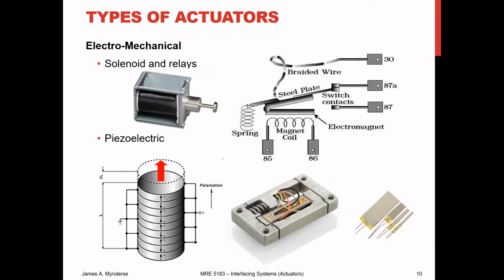But the stack there in the middle also has these little flexure hinges. So let me make sure my pen is working. So here is our stack, and then these little things are flexure hinges. And these hinges are made by removing material. So you cut away enough to leave a little bit of material there, and then it bends about that material like it would about a hinge. So it is a nice way to machine a hinge into something.